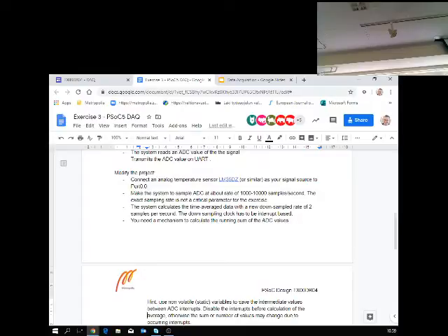So basically this A to D converter, you will modify it to run free at any rate between 1,000 and 10,000 samples per second. Actually, the A to D converters on this board are pretty fast by default. They are designed for continuous sampling, and 1,000 samples per second is typically how you sample some biometric signal.